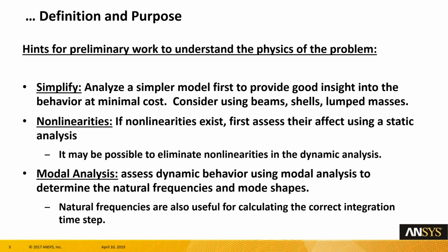The questions to ask are: is large deflection really important? Are the contact nonlinearities important? Is the material nonlinearity important? Maybe the material is going through plasticity in a very tiny area that it may not be that important, that it's not affecting the overall stiffness by much. And then of course, we need to do a modal analysis to assess the dynamic behavior. First we have to do a natural frequency and mode shape analysis. The natural frequency is going to be useful in calculating the initial time step.